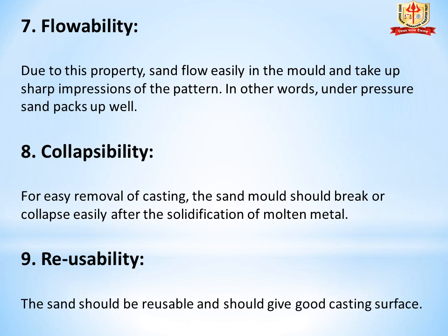Eighth property is collapsibility. For easy removal of casting, the sand mold should break or collapse easily after solidification of molten metal. Ninth is reusability. The sand should be reusable and should give good casting surface. These are some properties of molding sand.